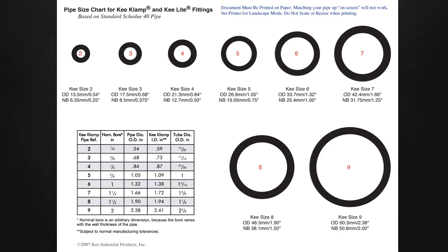Pipe schedules are directly related to the ratio of the working internal pressure as well as the allowable stress. So it's the ratio between the working internal pressure and allowable stress for that material of construction for a specific nominal diameter pipe. So say we have a 10 millimeter nominal diameter pipe.